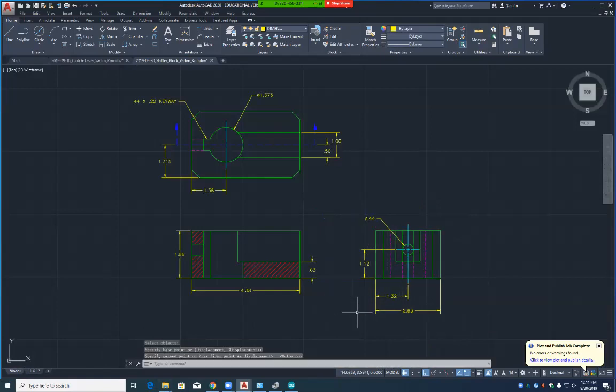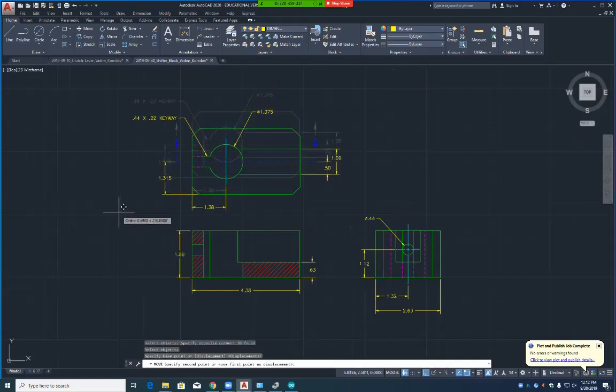Hey, Mike, so when you're done, the center point is like, go out to your circle. So draw a line. So scroll in there. A little copy. You can drop your center point. So copy. Don't pick it first. Enter the command first, and then pick. I'll pick the midpoint of that. Turn your snap off. Get rid of that snap right there. I just want to go to the center point, right?